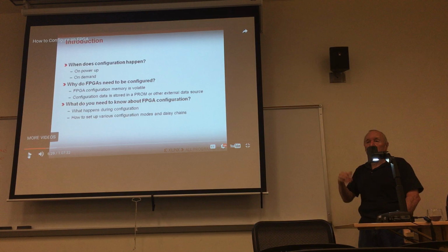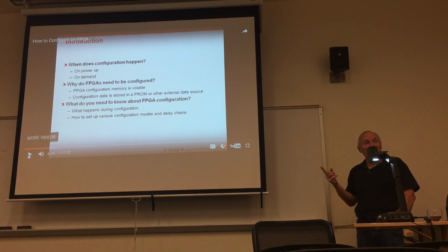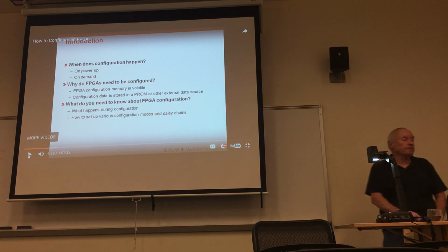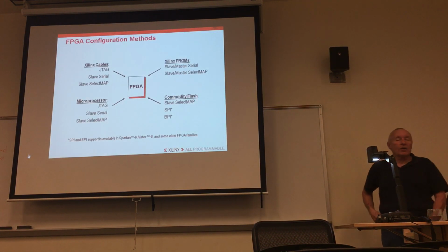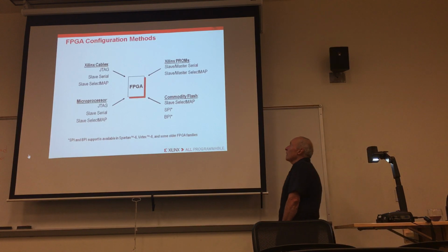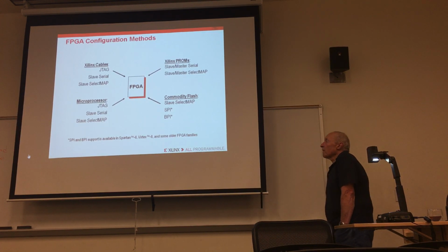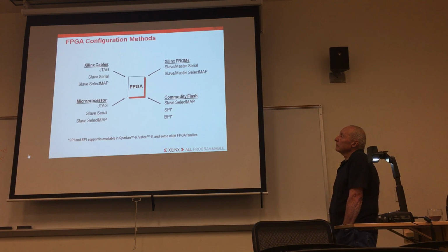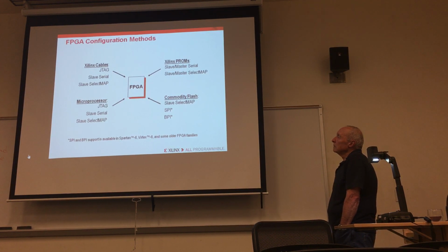I'm primarily going to focus on a system where you only have one FPGA that you have to worry about configuring. Well, there are lots of configuration possibilities to consider. The first we're going to consider is configuring via a Xilinx download cable. These cables allow the user to reconfigure their FPGA with only a download cable and their computer. The configuration modes described are used primarily for prototyping and debugging a design. These cables are low cost and are typically used to configure the FPGA in a JTAG configuration mode. We will discuss the additional hardware available in the basic FPGA Configuration 2 module.